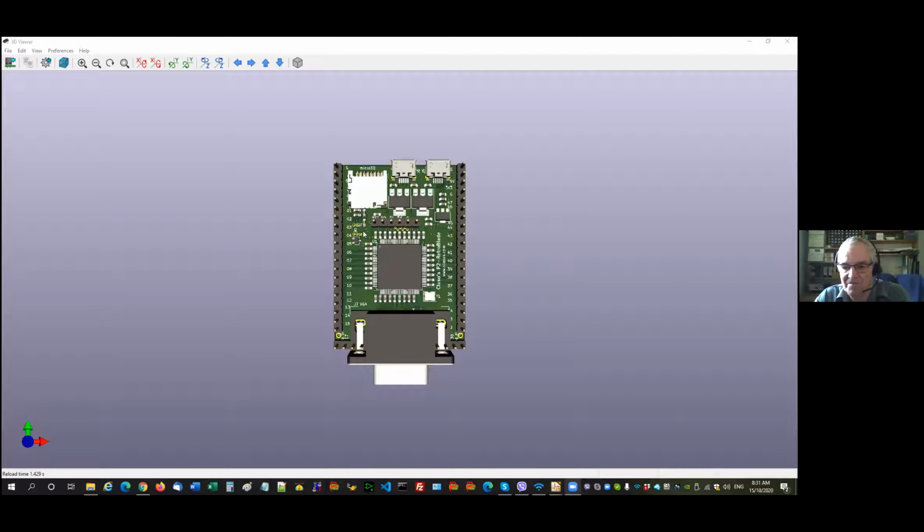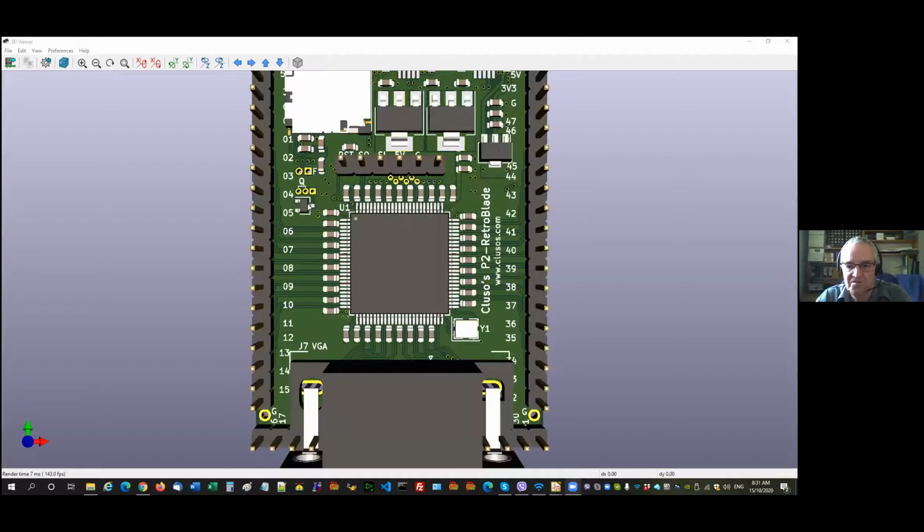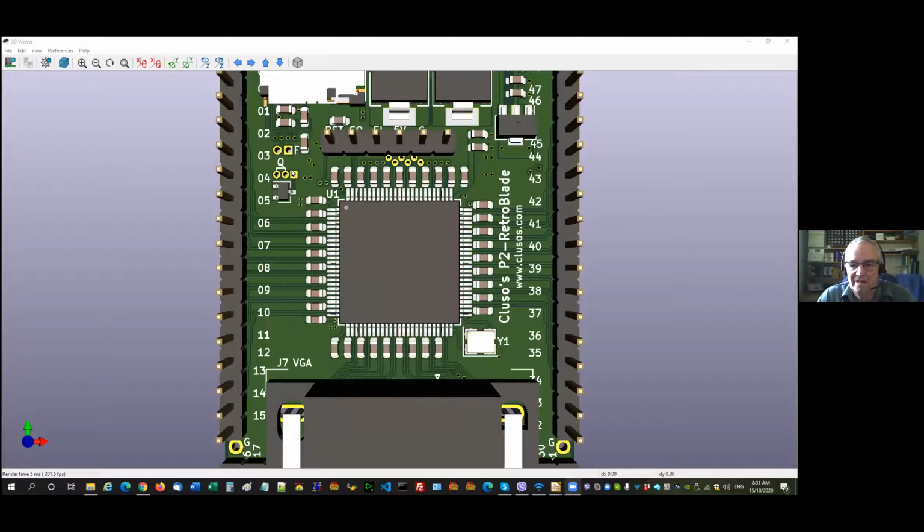And I have over here the little transistor reset circuit. So there's the transistor. And there's a little 3-pin 0.05 inch or 1.27 pitch, so the half size pitch, where you can put a link on, and the Q is marked for using the transistor. Otherwise you need to link the other two.